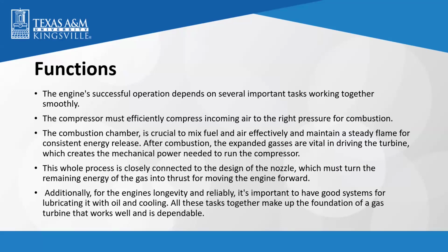The operation of our design depends on several important factors working together smoothly. Our compressor must efficiently compress incoming air to the right pressure for combustion. In our combustion chamber, the design is crucial to mix air and fuel effectively and to maintain a steady flame for consistent energy release. After combustion, the expanded gases are vital in driving the turbine.